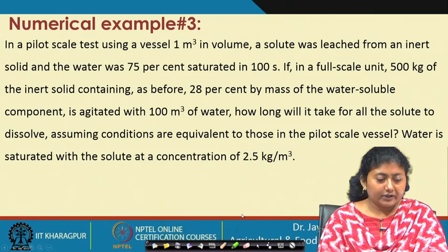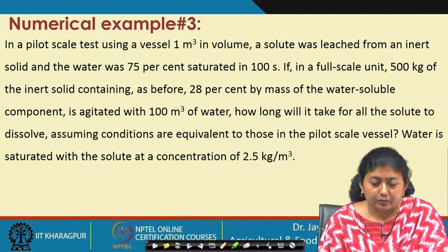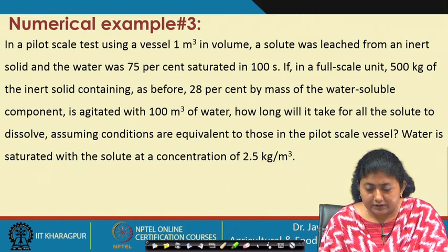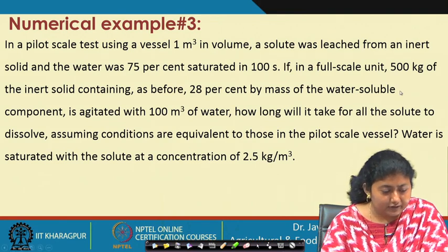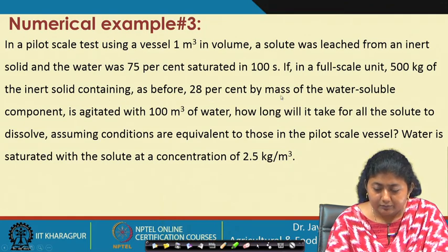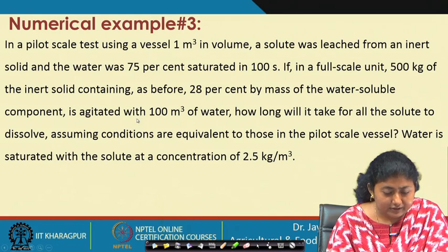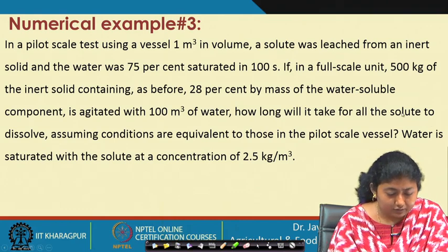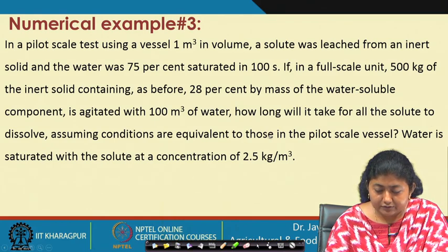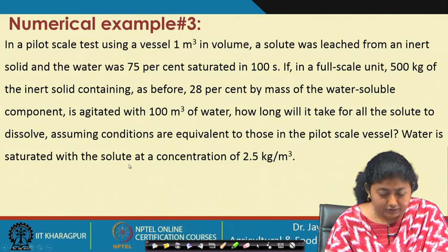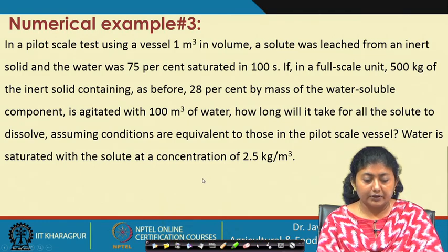So, let us see one example on that. In a pilot scale test using a vessel 1 meter cube in volume, a solute was leached from an inert solid and the water was 75% saturated in 100 seconds. If a full scale unit, that is 500 kg of the inert solid containing as before 28% by mass of the water soluble component, is agitated with 100 meter cube of water, how long will it take for all the solute to dissolve? Assume conditions are equivalent to those in the pilot scale vessel and water is saturated with the solute at a concentration of 2.5 kg per meter cube.